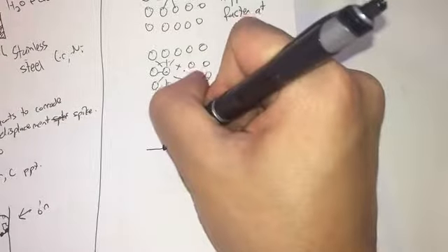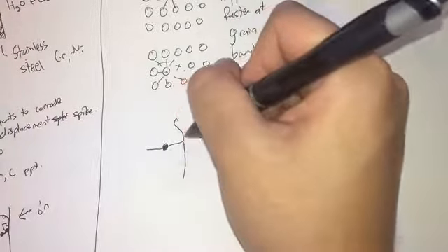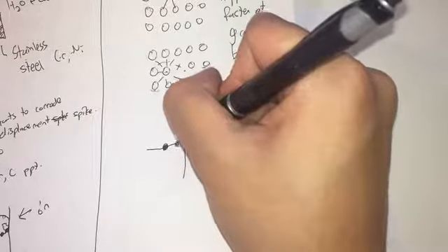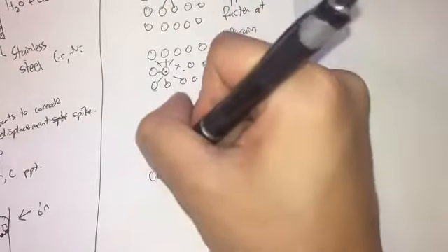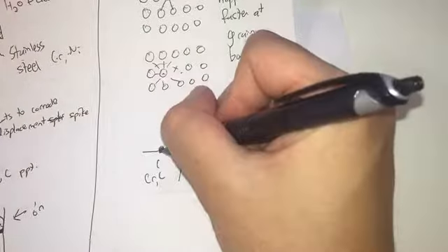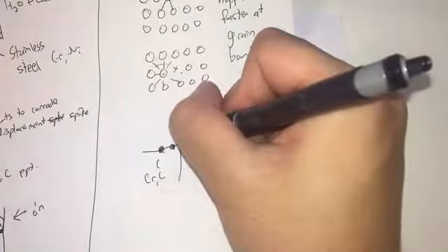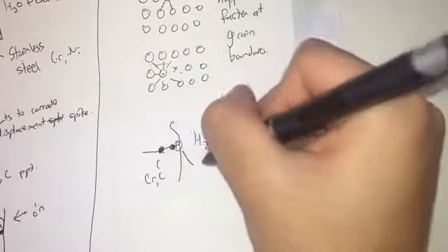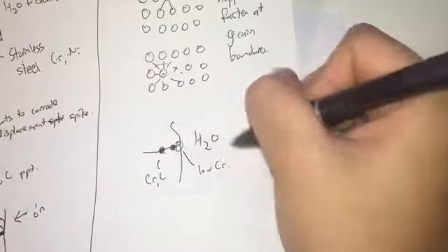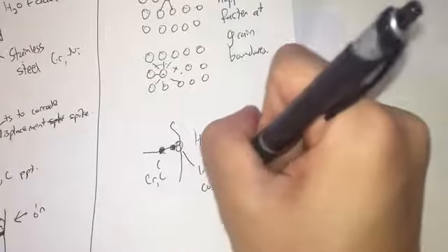So this is water. Let's say you have vacancies being created here. So you have these chromium carbon precipitates, which are generally not a problem in themselves, except that over here is low chromium. So the water sees this low chromium and this starts to corrode.